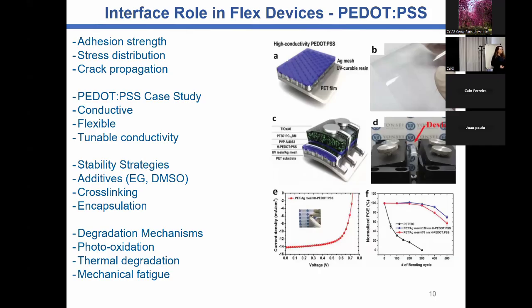But sometimes we don't find any processable material with efficiency as high as PEDOT:PSS, then we must somehow deal with the same material but with different strategies. For instance, put some additive or cross-linking to increase the adhesion between the layers.